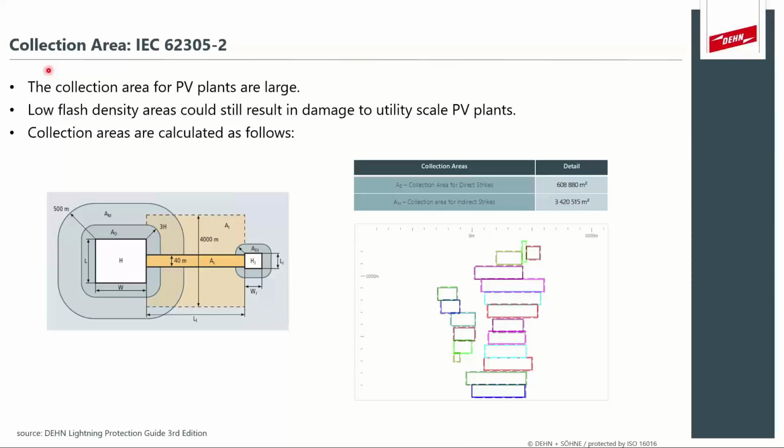Unfortunately, with something like a PV plant, which is a very open area, there's no real way to protect people within the PV area from direct lightning strikes. People in the outside zones or outer areas cannot be protected against lightning. But what we then do is incorporate evacuation techniques and systems, with early detection, to get people out of the plant when a lightning storm comes in. So we mainly focus on the economic risk for PV plants, to protect the actual asset.